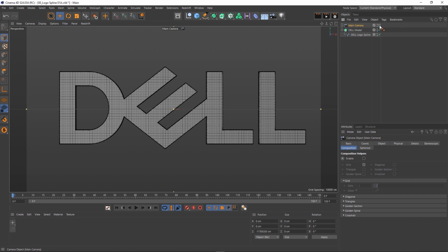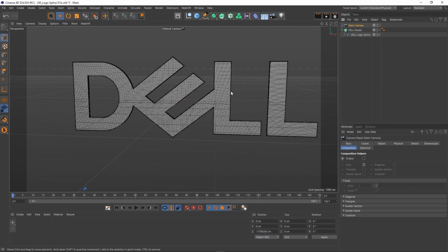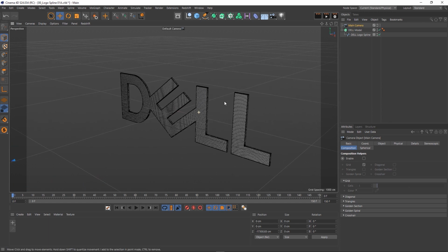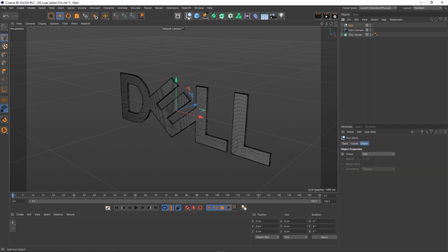Now, back to the deformations. Let me deactivate the camera, because I don't want to move it by mistake, and then just navigate using my default camera. I'm going to create 2 bend deformers. So first of all, let me fold this, and let me create a null at the center of the world. I'm going to put it here, call it Def, F for deformed, and then I'm going to create a bend deformer.